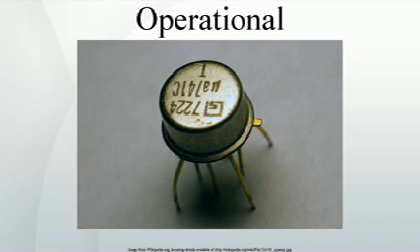Power considerations. Modern integrated FET or MOSFET op-amps approximate more closely the ideal op-amp than bipolar ICs when it comes to input impedance and input bias currents. Bipolars are generally better when it comes to input voltage offset, and often have lower noise. Generally, at room temperature, with a fairly large signal, and limited bandwidth, FET and MOSFET op-amps now offer better performance.